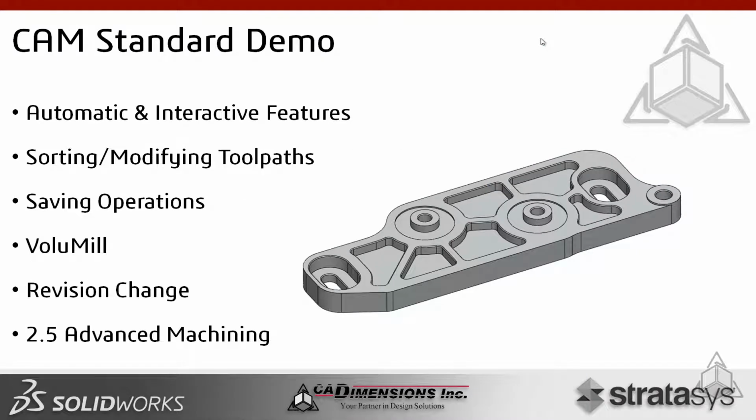So what are we going to do during the demo? I'm going to talk to you about how SolidWorks CAM automatically defines those features, that automatic feature recognition like what we just talked about. I'm also going to show you how we go in and manually define features if it doesn't grab everything. We'll talk about how we sort and modify our tool paths, maybe adjust the size of things, maybe change the pocket size, strategies. We'll save the operations back to the database. I'll explain that a little bit more in depth. We'll talk about VoluMill and that high-speed machining. I'll go in and make a revision change so that you can see what happens when you change a dimension. And then we'll get into 2.5 advanced machining.